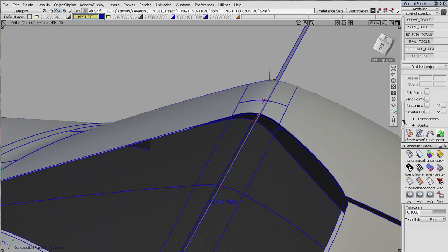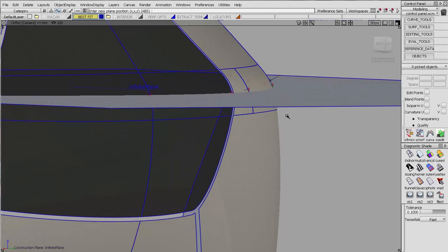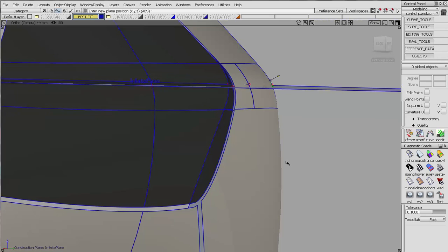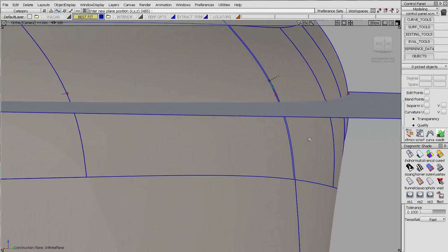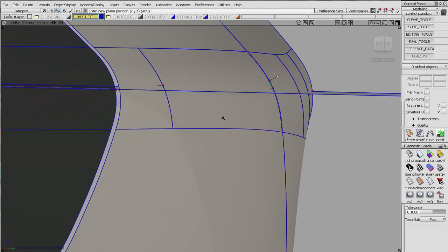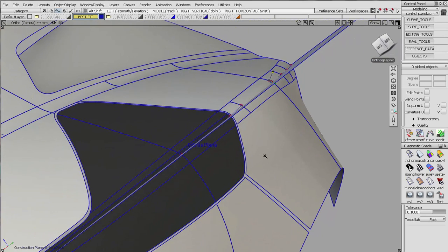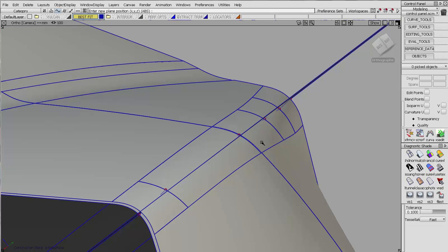So if we zoom in here and I use some of my azimuth and elevation controls, see I can rotate this plane, get it square to grid, and then I can roll it this way, and I can judge if those points all sit on that plane. And you can see that's an average of those points, right? This point's above, on, below, on, right? And that gives me an idea of what the shape of that fillet is. And you can see right there, that fillet tends to move around and follow off that plane.